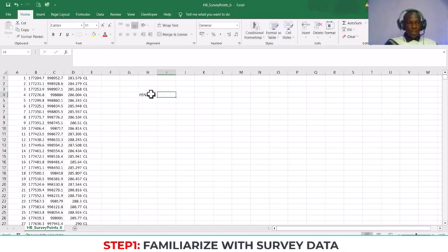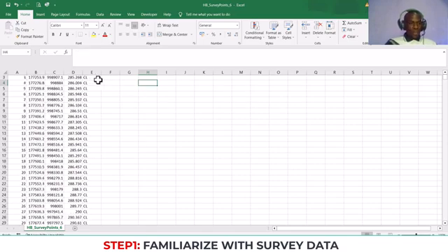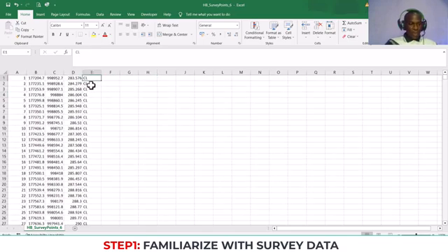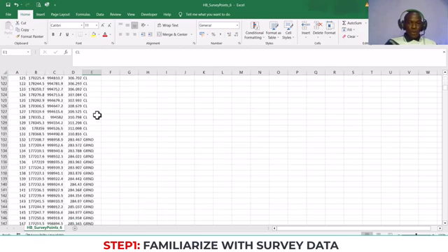I'm just saying this because you will see it shortly when we go to Civil3D. You have to understand how your points are arranged. So it's arranged in this format here: P-E-N-Z-D. Points, eastings, northings, Z elevations, and then D descriptions. So what are these descriptions? We have CL here. CL means center line. If you go down, you will see GRND. GRND is short for ground.